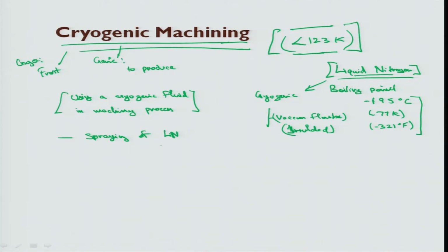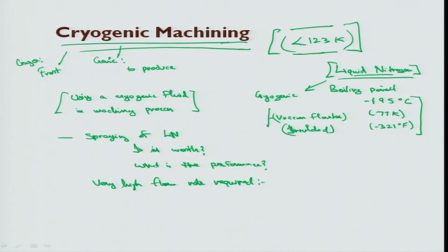So is it good to spray liquid nitrogen? Is it worth it, I would say? What is the performance? Now the issue here was the liquid nitrogen evaporates very quickly. So during spraying, the flow rate that is required was very high. But even with high flow rates, the nitrogen mostly evaporated before even reaching the cutting. So the performance was not good.